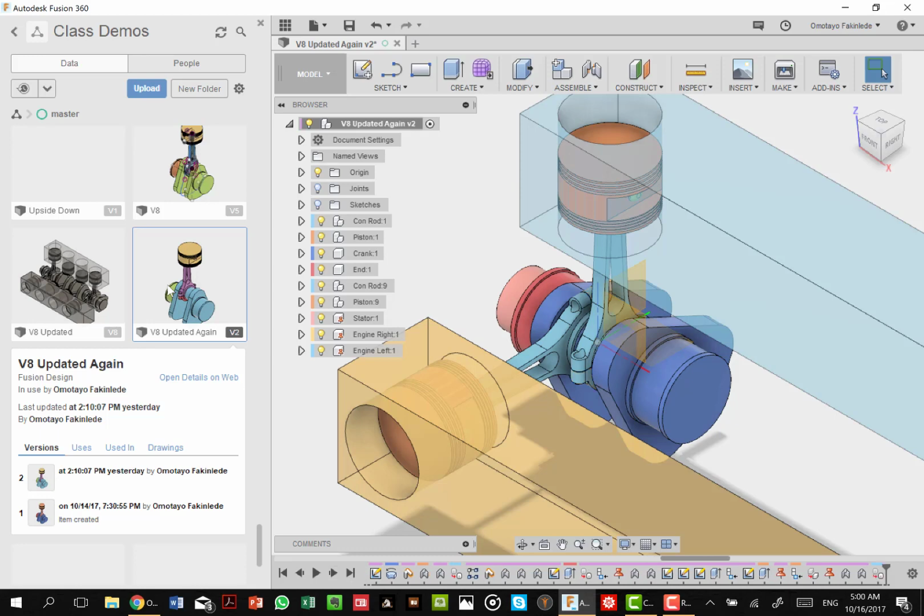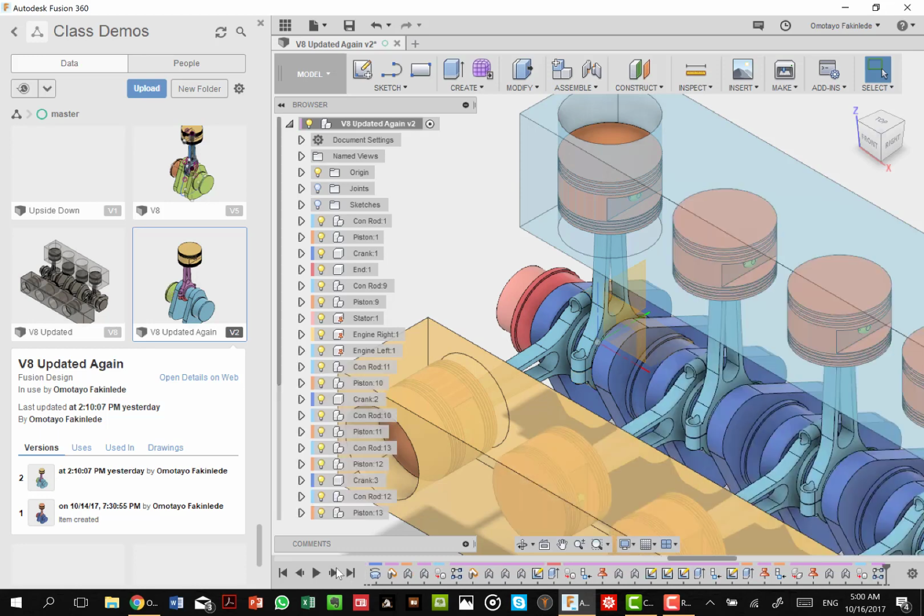So from this point on, it's a matter of now doing a pattern. Create pattern would give us a replication of all these things we have done. Remember that as a result of create pattern, some joints will be transferred, some joints will not be transferred. The joints that are transferred are the joints that are entirely contained within the components.